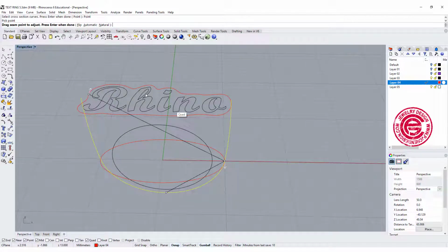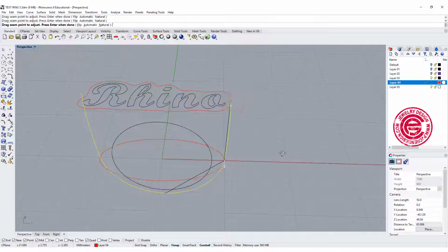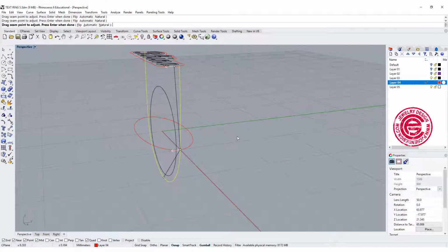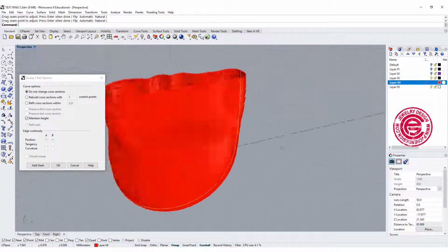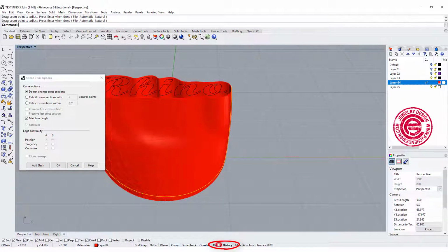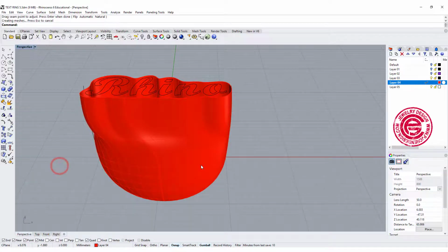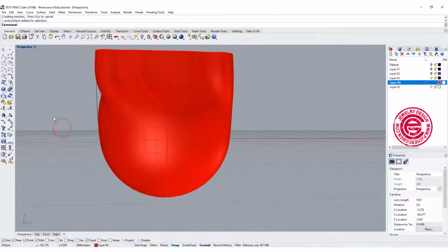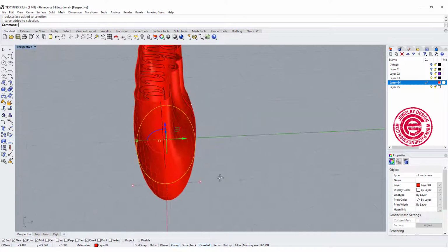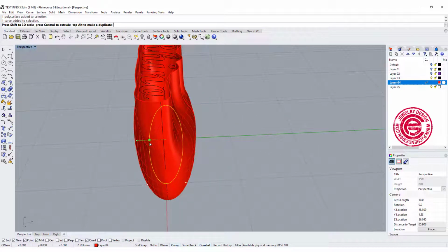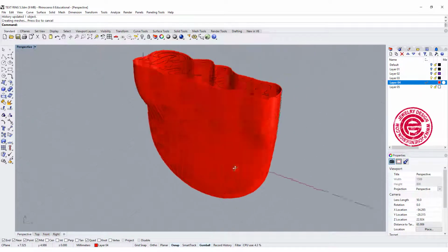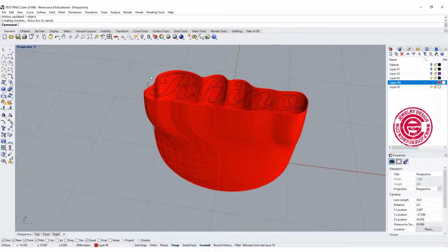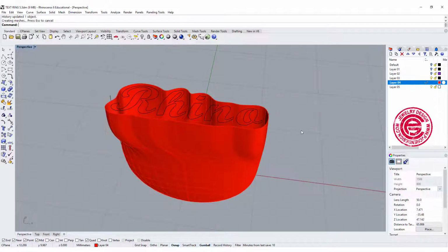Make sure that we align all the arrows and the direction as well, and they are facing the same direction. Let's click OK. Then you will get this shape over here. If you turn on the history and then click OK, and we feel like the middle part is a little bit too fat and I want it to come in a little bit, then you will be able to do additional edits there. Notice that it follows the edge really well over there.